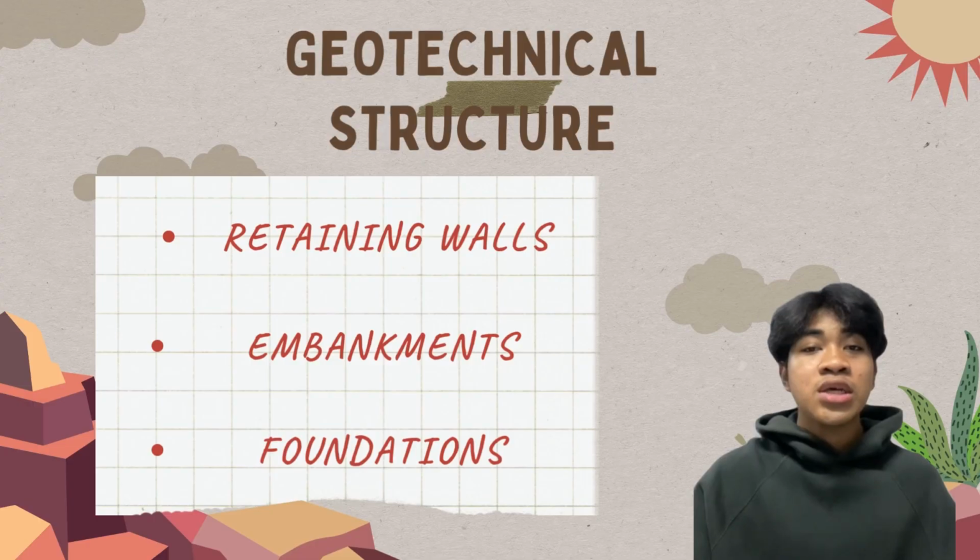For foundations, saturated soil reduces bearing capacity and increases settlement risk. In such cases, deep foundations like piles are used to reach stronger soil layers. Overall, saturated conditions require careful design and good drainage to ensure the structures remain safe and stable.